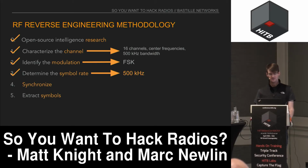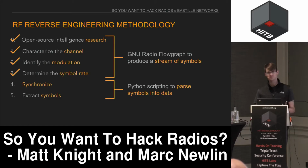So at this point, we've characterized most of the critical PHY elements that we need to be able to translate what's happening in the wireless domain into bits on a disk. So we're going to take these first elements and turn them into a GNU Radio flow graph. It's going to produce a stream of symbols coming from our software-defined radio.